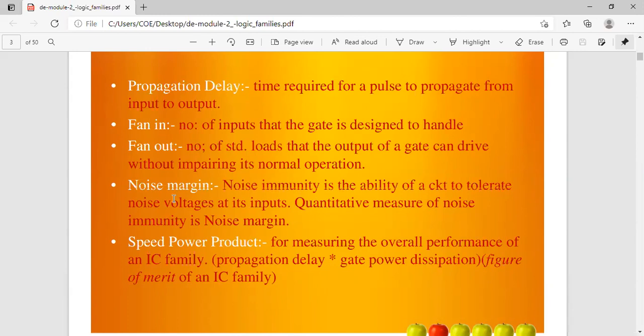The same thing you might have studied in microprocessor based experiments, such as the keyboard interface circuit, the same thing in another way, debouncing. Whether it is your computer keyboard or your button type mobile phone, when you press a key you can realize this noise margin. Whenever I press button 1 or 2 and then release, during pressing and releasing it does not exactly reach the final state or final level. When you press, it does not go immediately, sir, it takes some duration.